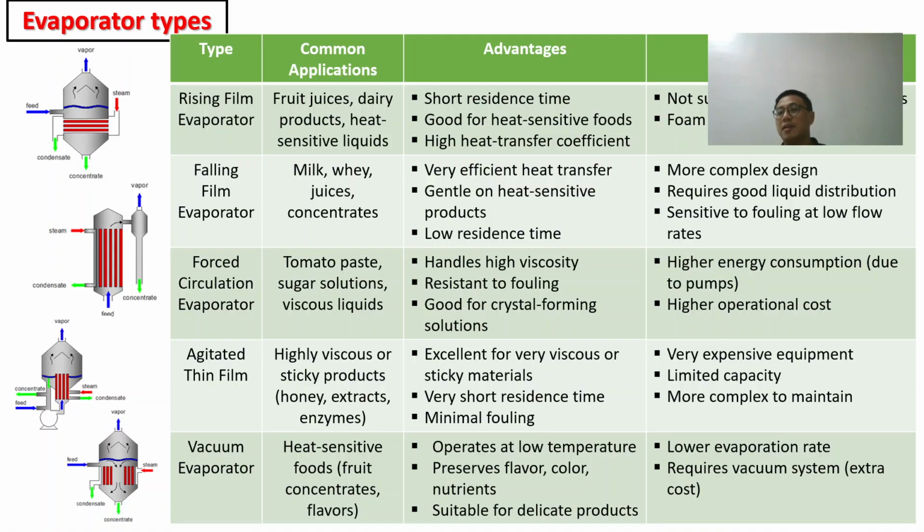That's why it's expensive. Limited capacity, so to have the agitator inside, we have limited room to ensure proper agitation, so the capacity is small. More complex to maintain. Okay, so we have more components as usual. We need more care, more maintenance, more procedures, and complex labor experience to maintain and to operate this evaporator.